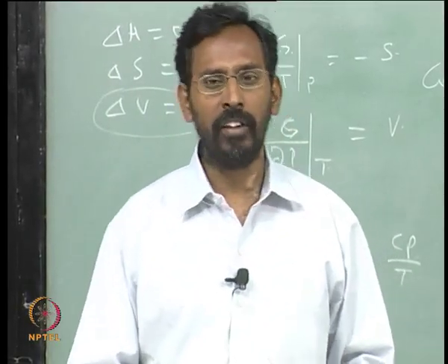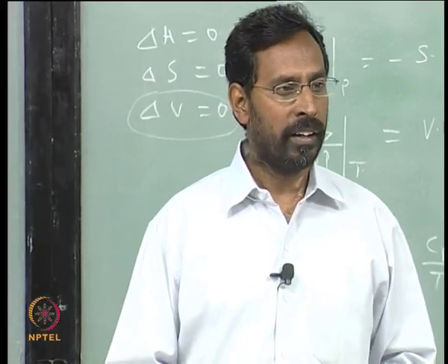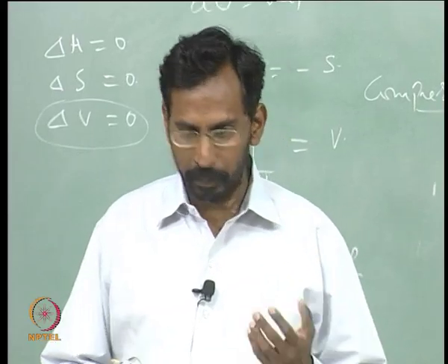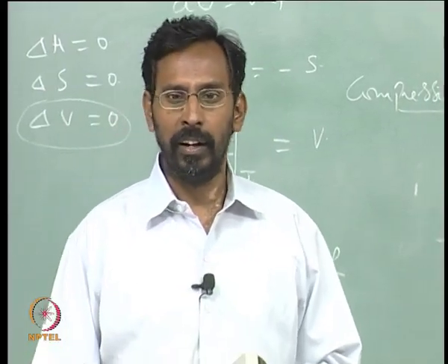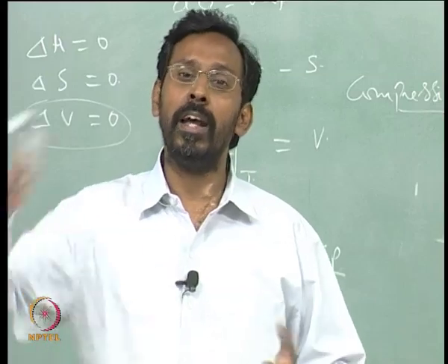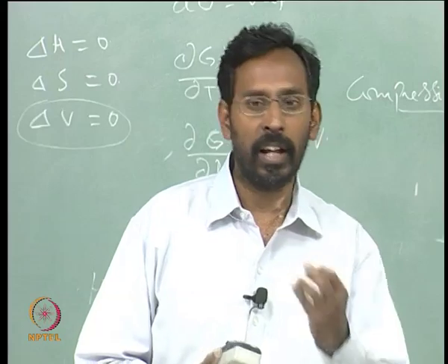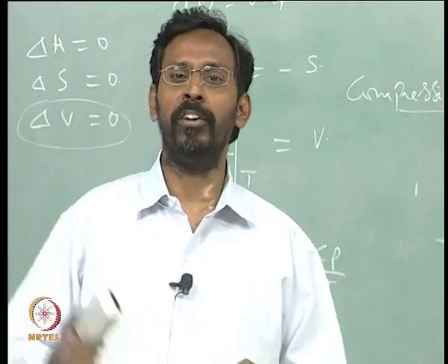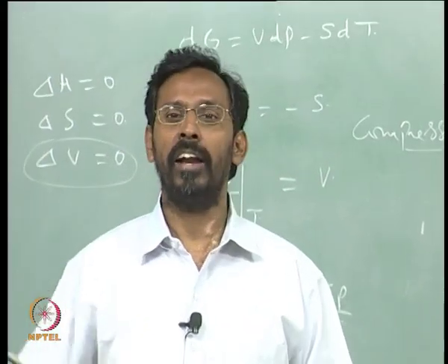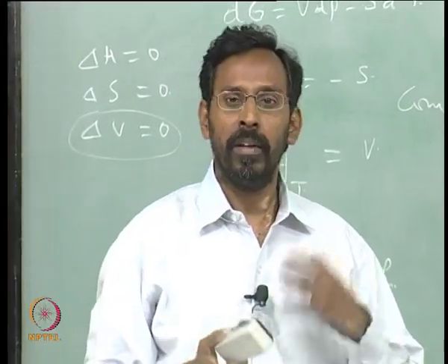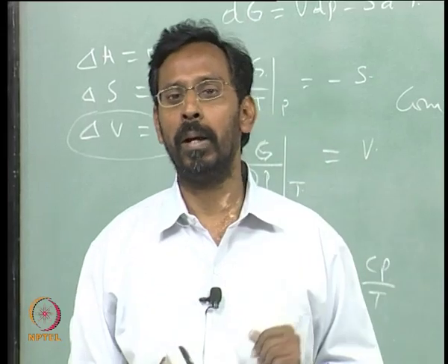Yes, to a large extent diffusivity. When we take a metal, of course there are many concepts. One is diffusivity, where you tend to add metals with a higher melting point so that the diffusion is slower. You take, let us say, aluminum, add iron to it, add titanium to it, or add vanadium to it, which are all high melting metals. Added to aluminum, the tendency is that the diffusion becomes slower.